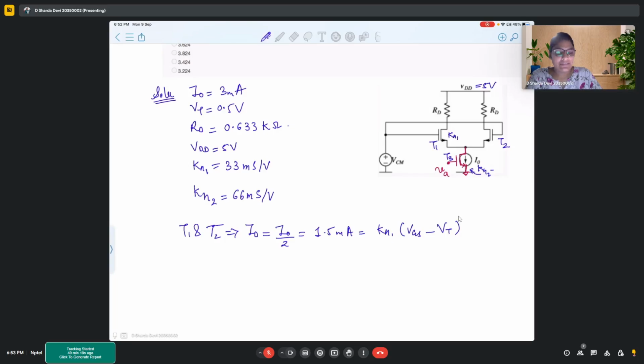So when you see a practical transistor circuit, we will come across them. There you will observe that all the components, say resistance, capacitance, and here the current sources, are designed out of MOSFETs. So in a practical scenario, your current source is actually designed of a MOSFET.